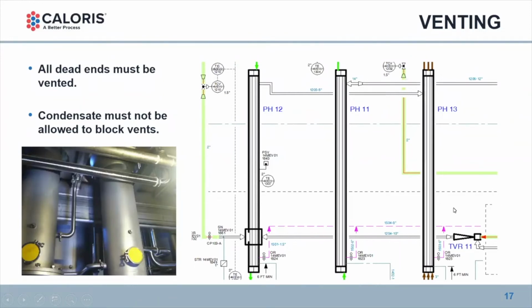And another key point here, you'll see at the bottom, and also shown in the picture, the pink lines with an orifice. Those show the vent line being pulled out of the bottom of these shell and tube heat exchangers. And below that, the solid line is the condensate coming out. We need to design the condensate removal of any shell and tube heat exchanger so that the condensed water vapors are pulled out and do not fill and start to block that vacuum outlet. Otherwise, we cannot vent the non-condensable gases out of the system if we start to block those.